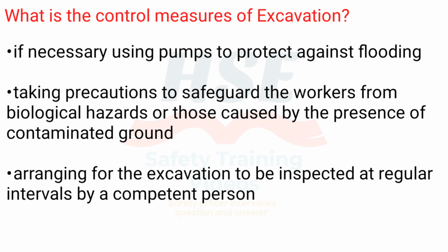Taking precautions to safeguard the workers from biological hazards or those caused by the presence of contaminated ground. Arranging for the excavation to be inspected at regular intervals by a competent person.